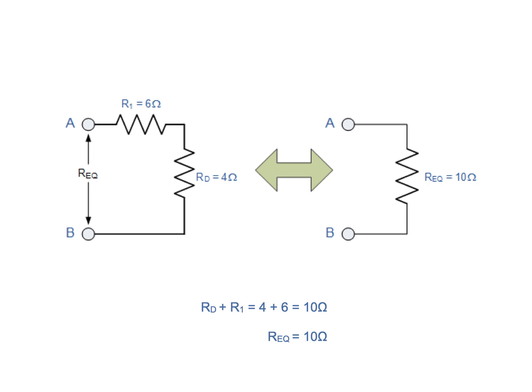This step will allow us to reduce the complexity of the circuit and help us to transform a complex combinational resistive circuit into a single equivalent resistance, remembering that series circuits are voltage dividers and parallel circuits are current dividers, subsequently allowing us to calculate all the currents and voltage drops in each of the branches.